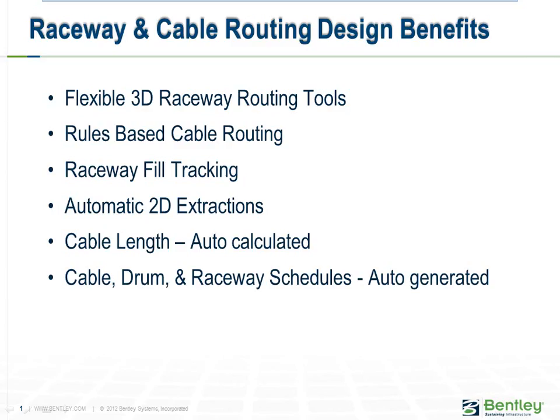In review, here are the raceway and cable routing design benefits. What we saw in the demo was flexible 3D raceway routing tools. We also saw rules-based cable routing, as well as raceway fill tracking, automatic 2D extractions. We saw that the cable length was automatically calculated when we routed the cables through the raceways. And also, various reports can be generated, such as the cable reports, drum reports, and raceway schedules.